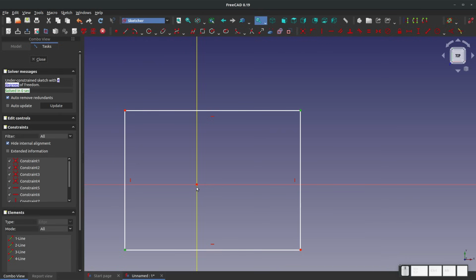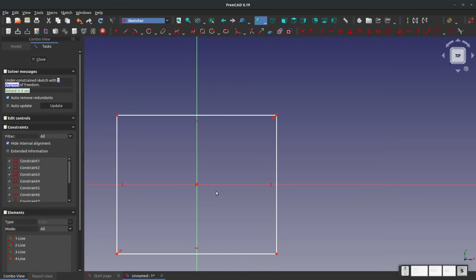the origin. We're going to say S for symmetric. That's a hotkey, right? Saying S for symmetric is the equivalent of clicking on this button, which, as you can tell, has a little S in parentheses in that description. So almost all these are hotkeys, and honestly, I just use the hotkeys more than anything, but I'm trying to use these buttons to make it simple. All right, so we hit S for symmetric.